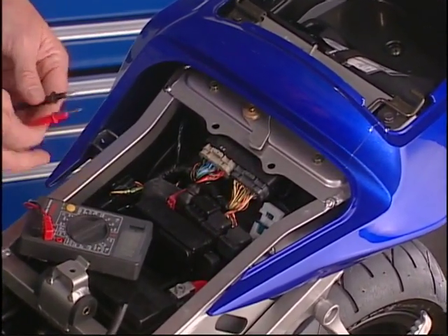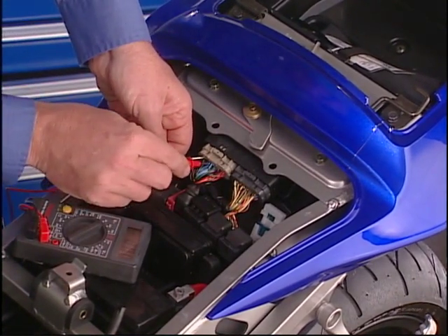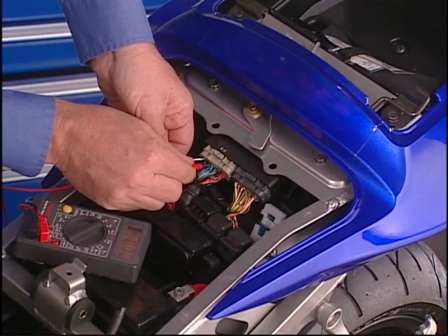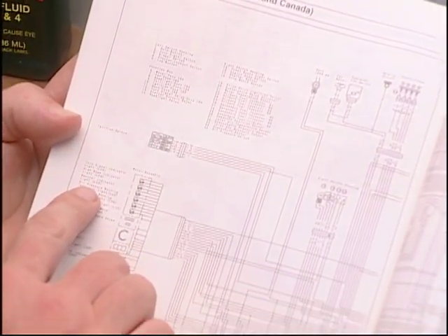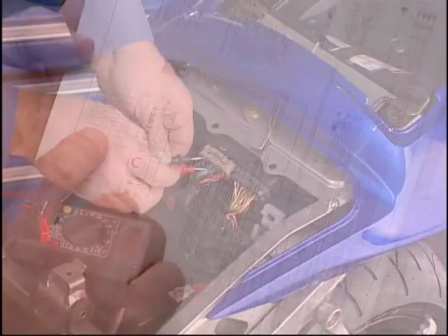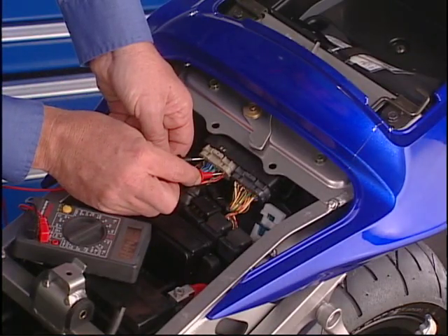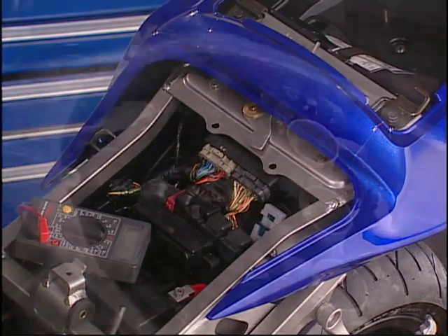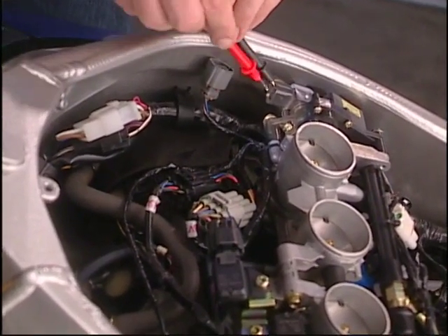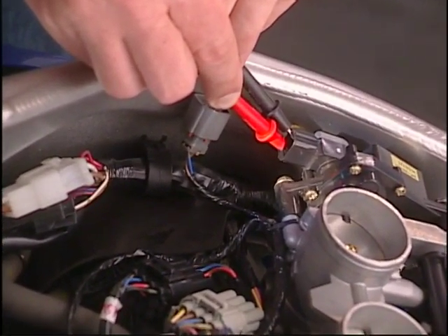For example, when checking a circuit that receives its operating voltage and ground from the ECU, perform the test at the ECU connector. Using the vehicle's wiring diagram, locate the wires coming out of the ECU to the component. Now perform a voltage test to see if the component is being supplied voltage and a ground. This eliminates the possibility that there is a problem between the supply and the ECU. Always test a component before replacing it and perform all of the tests described in the service manual to verify the condition of the component.